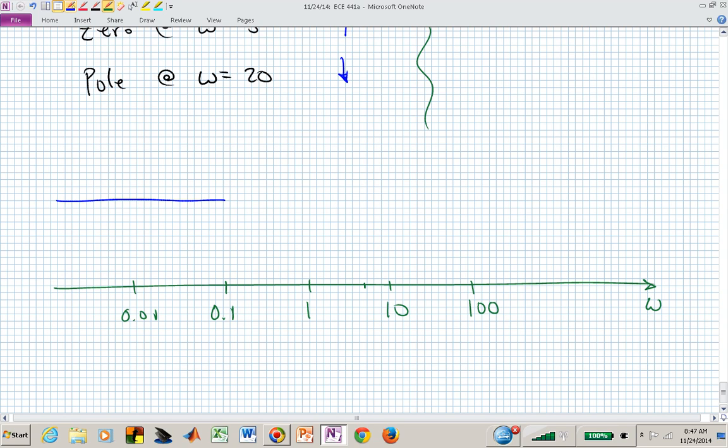I started here at 20 dB. And let's say this is 0 dB. This is now G in dB. I know that after a decade, I better be down 20 dB, shouldn't I? So my gain curve is going to be sloping with that slope until I reach 5.